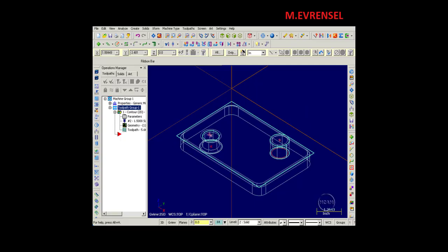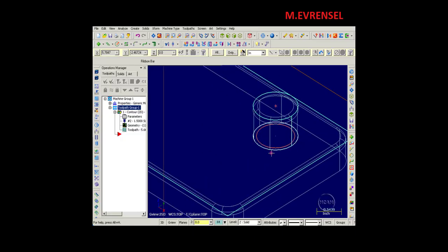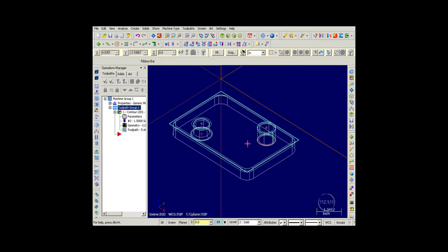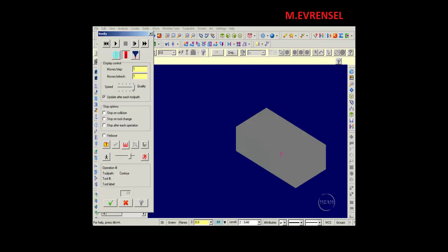I've got some points which I'm going to utilize to create the tool paths, and then this inner circle right here is being used in a tool path which is already created for a slitting saw to undercut this boss that's sticking up to act as a thread relief. So let's go ahead and take a look at this tool path and verify. Go into verify. Now I'm just getting a block of material here.